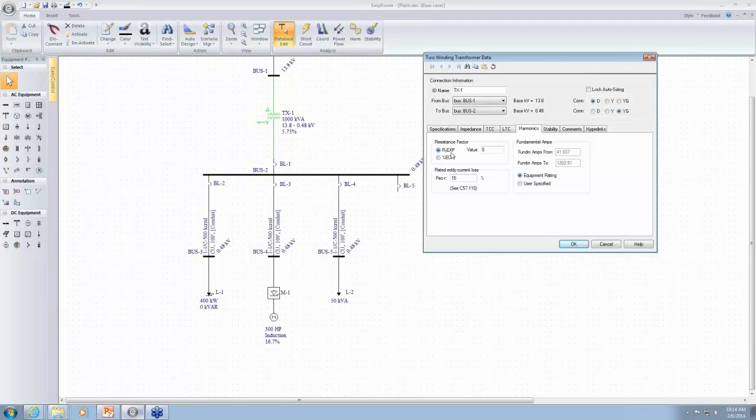If you look at the REXP, a typical value we said earlier for simple conductors might be 0.5 to account for skin effect. If we keep on adding the other effects like proximity effects and core losses in the transformer core because of the harmonics, then a typical value might be close to 0.7 as the exponent. So let's model it as that.